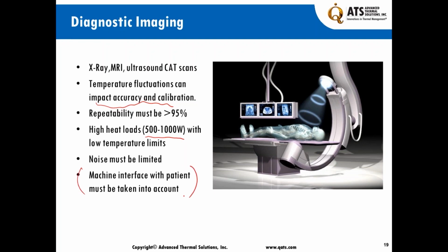From the thermal standpoint, this is very important because no surface can be more than 40 degrees C, at the most 41 or 42. And anything over 42 is a red flag. Most equipment manufacturers try to make sure that their equipment is below 40 degrees C as a comfort temperature for the patient. And again, you've been to doctors' offices or hospitals and so forth, where your temperature, pressure, etc. are taken, and your equipment cannot be too hot or cause discomfort or possibly skin burn.